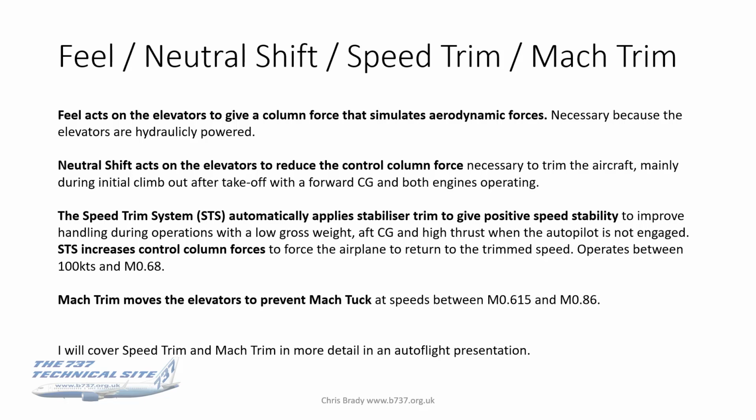feel acts on the elevators to give a control column force that simulates aerodynamic forces. That's what feel is. And this is necessary because the elevators are hydraulically powered. Neutral shift acts on the elevators to reduce the control column force necessary to trim the aircraft. It's mainly during initial climb out after takeoff with a forward CG with the engines operating.